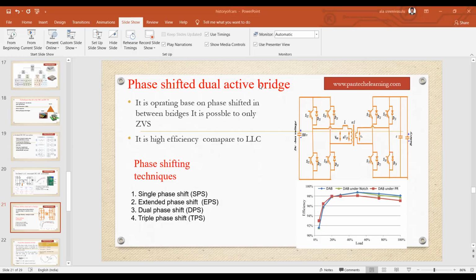Using mathematical equations, learn how to build the model in MATLAB. I said, for the non-isolated DC converter topology, if you derive the mathematical equation, you get V0 as Vin by 1 minus D. If you apply KVL, you get one mathematical equation. You will get the inductance formula and the capacitance formula. From that, if you have an equation, you can build it easily using the SIMULINK inbuilt blocks.